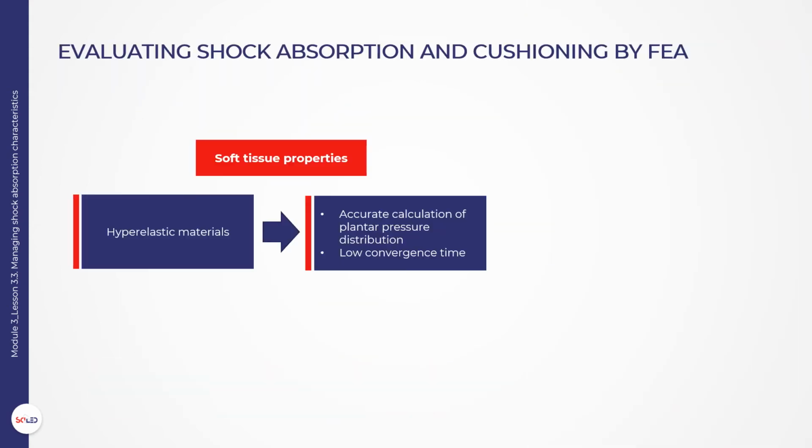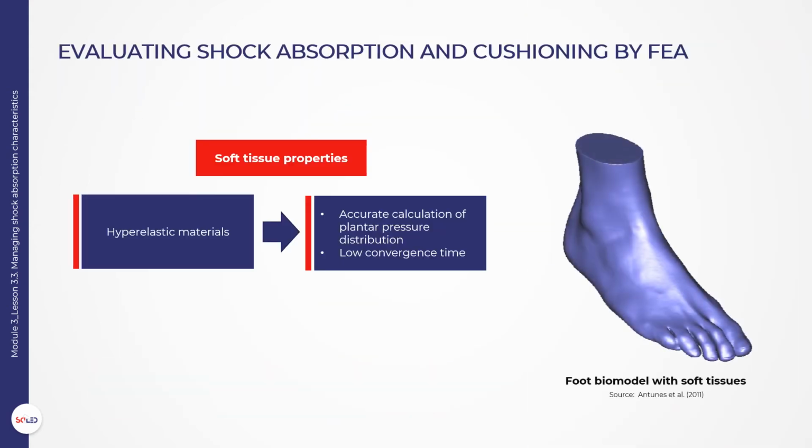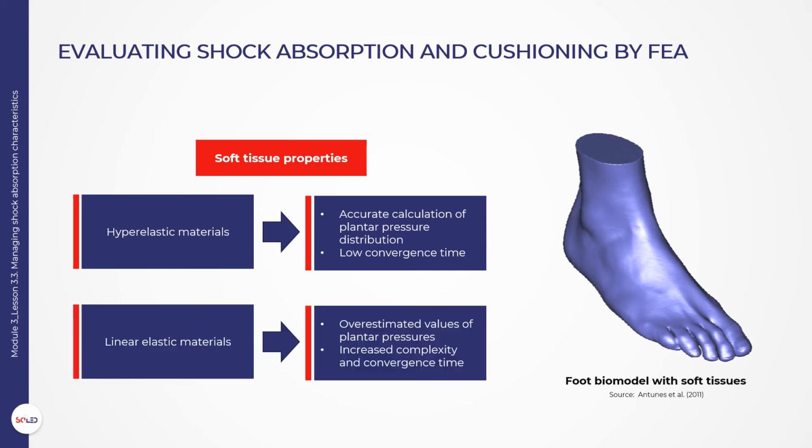Modeling soft tissues as hyperelastic materials is necessary to accurately calculate the plantar pressure distribution. The use of linear elastic material properties may lead to significant overestimates of plantar pressures. However, this may increase complexity, time to convergence, solving of the equation systems, and burdens optimization simulations.